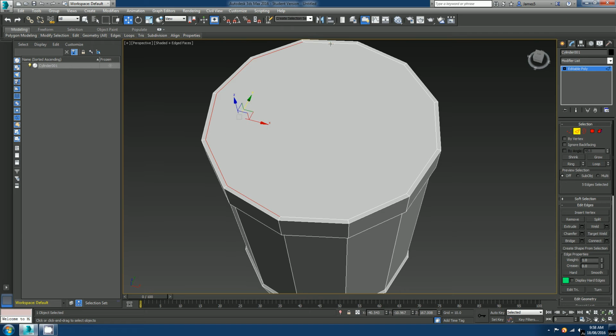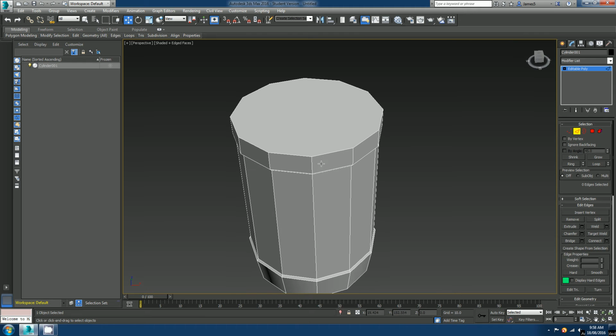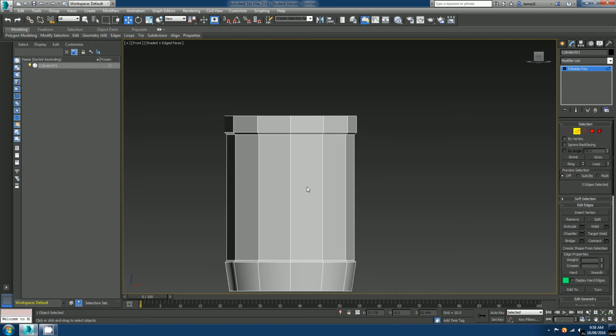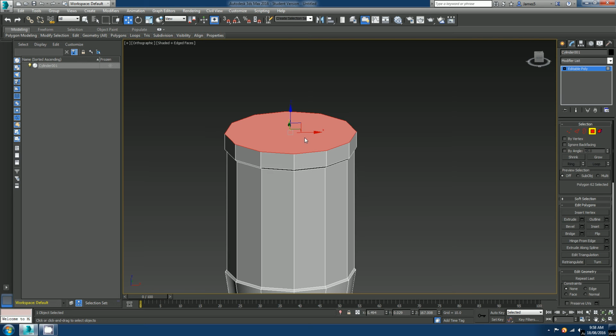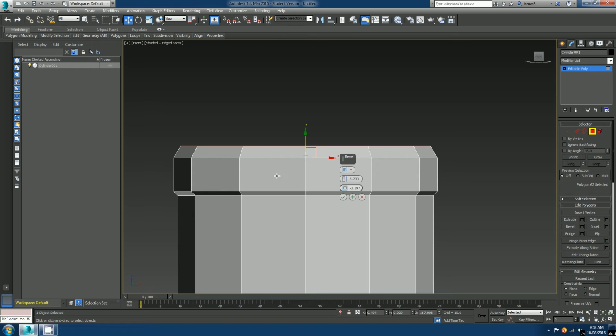So I'm going to just take all of these edged faces and I'm going to press Control and backspace. That's going to remove the edged faces, but it's not going to delete the face. Okay, let's continue. Let's go ahead and try that again. So let's go ahead and bevel, go to the front view. That should fix that problem, and it has, so that's all good.